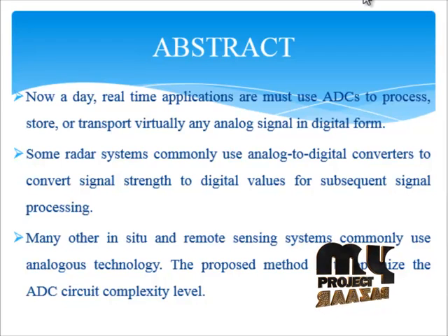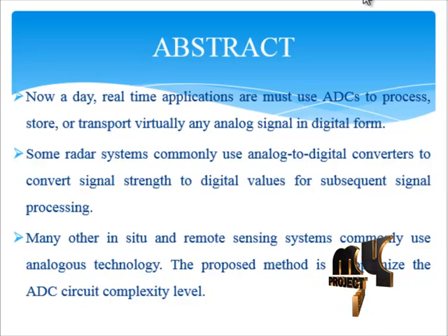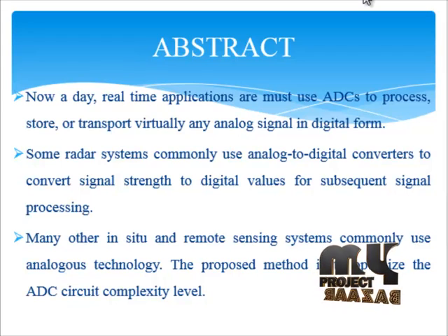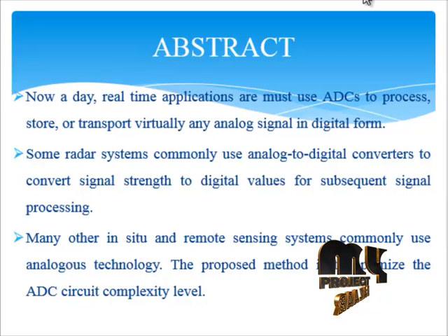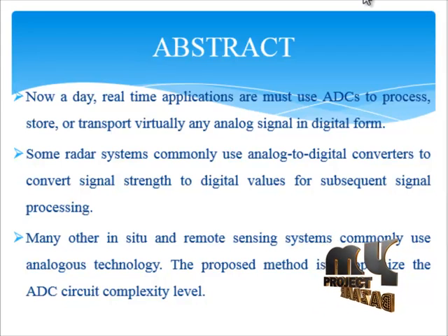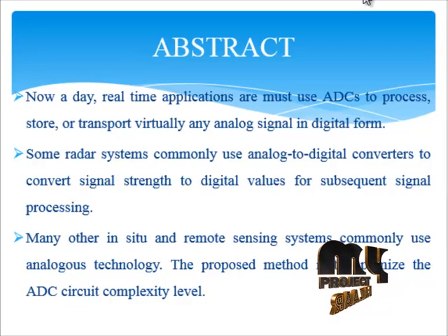We are using the SFDR, and the ADC performance is restricted by the front-end sample and hold, whose non-linearity is carried into the final digital output. We also get gain error, and in the ADC transfer function there is capacitor mismatch between the feedback capacitors, and a jump in the transfer function.